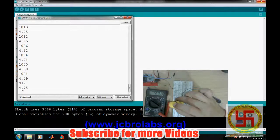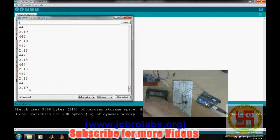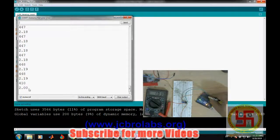So you can try it at your end as well. Let's set some random value, so it is 2.05, and on the terminal it is saying 2.18, so there is a mismatch of 0.1 volt. Generally this mismatch remains 0.02 or less than 0.02 volt. Or there could be a reason that we are providing the power supply from this board only, so it is varying. Okay, that is fine.